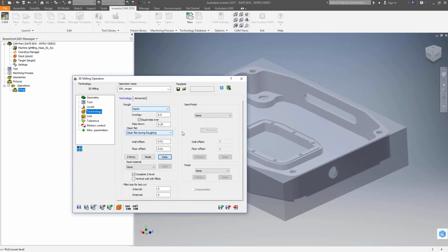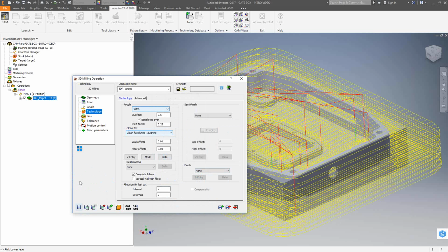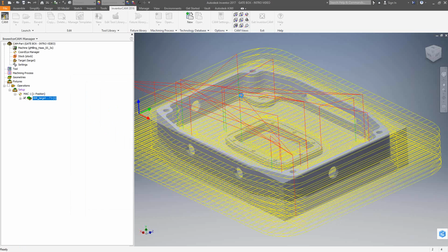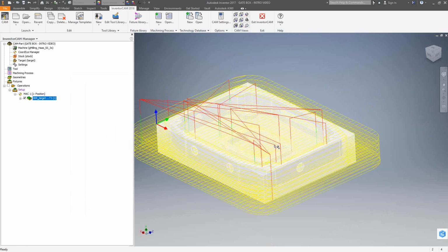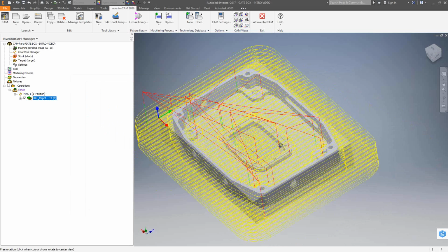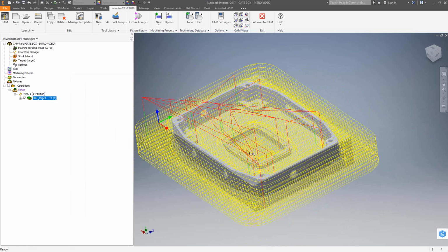Likewise, if I were to do this as a finishing toolpath, I have the finishing options in the lower right corner, and some of these are similar to the other strategies you'll see with some other finishing toolpaths later in the series of introductory videos. So let's just do a save and calculate on this, and we'll see how the 3D milling applies a 1/2 inch end mill toolpath to this part. So essentially what you see is my 1 inch working area on all sides. If I just kind of move this a little bit, you'll see that it's essentially just a zigzag pattern back and forth.